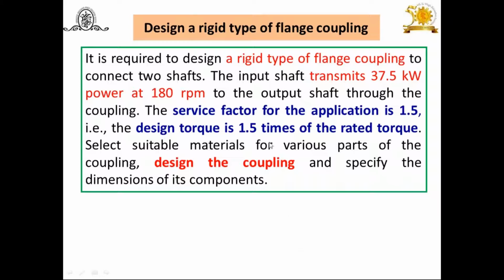Dear students, this is the problem statement. What we have to do today is design a rigid flange coupling. The input shaft transmits power, and RPM is given. Service factor is also given. We have to select a suitable material and design the coupling. This is about the problem statement.